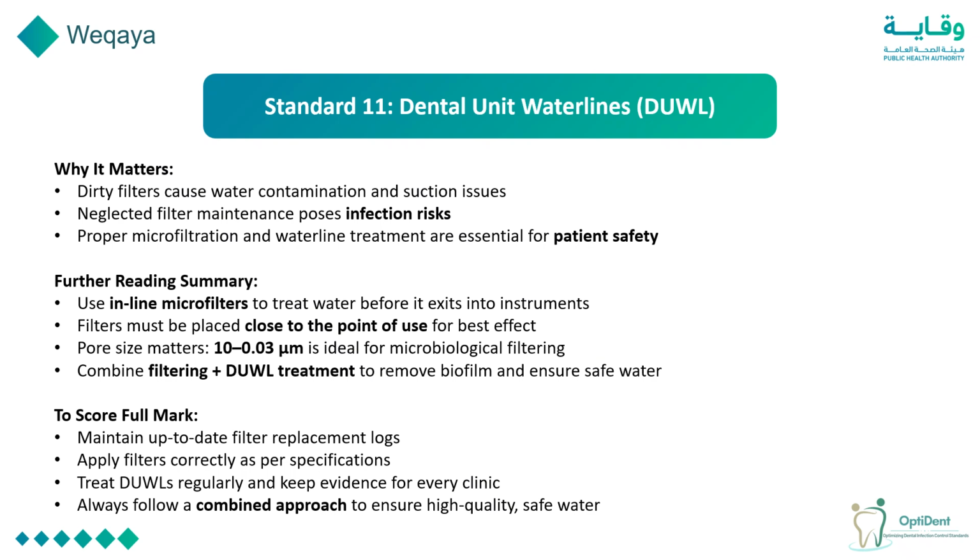Always place filters as close to the point of use as possible to maximize their effectiveness. The bore size matters. A range between 10 to 0.03 micrometers is ideal for effective microbiological filtration. For optimal results, combine filtration with regular dental unit water line treatment using chemicals to reduce the biofilm formation and ensure consistently safe water quality.